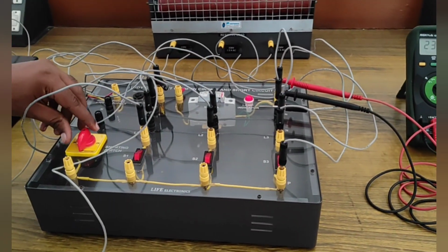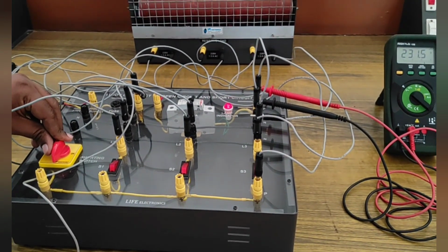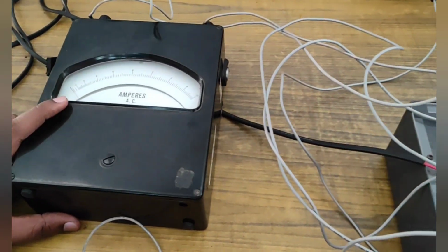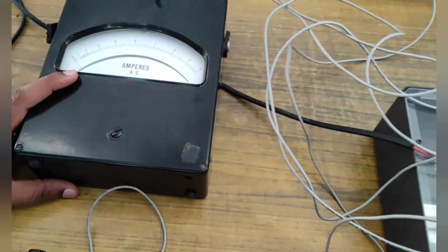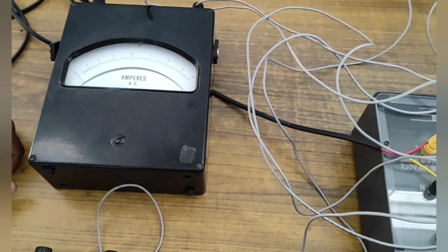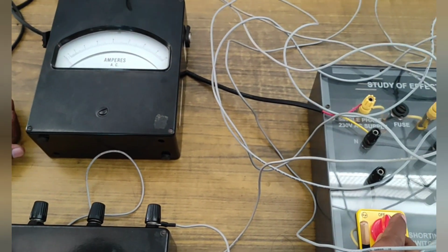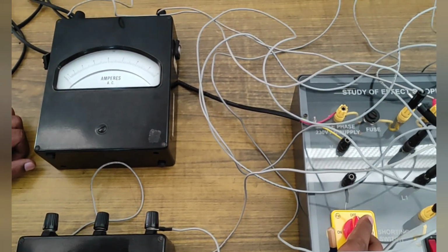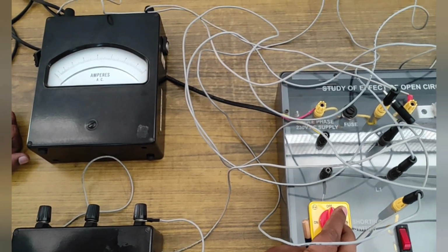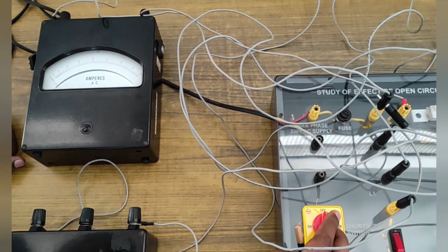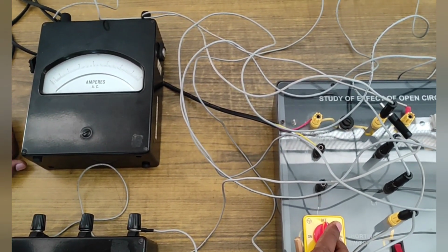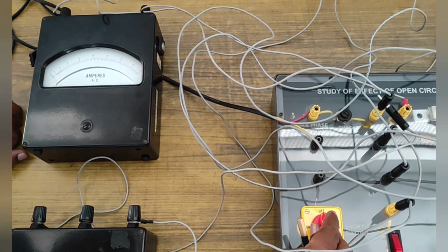Here there is a short switch, you just need to turn on the short switch. But here you can see the fluctuation in the ammeter while turning on the short switch. Just you can see here the fluctuation. Whenever the short circuit occurs, immediately the current becomes maximum and the voltage becomes 0. After the short circuit, the current becomes 0 because of the fuse. The fuse will be tripped and the MCB will be tripped. So this is one of the processes for short circuit analysis without applying load.